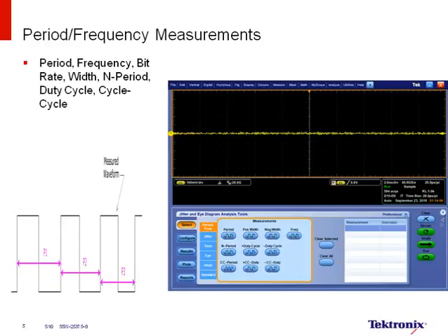Let me illustrate with an example. Let's assume that you're characterizing a 100 megahertz clock, and the peak-to-peak jitter spec is, let's say, 100 picoseconds. You make a measurement on this clock, and you measure 99 picoseconds. Did it pass spec? It certainly appears that it did, because 99 picoseconds is less than 100 picoseconds. However, if you continue to wait longer and make this measurement over an extended period of time, there's a very high likelihood that the measurement you make will exceed 100 picoseconds.